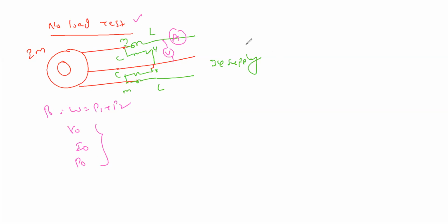What is its equivalent circuit? For a transformer under no load, we keep only the shunt elements and neglect the series elements. But here what will happen, we can't neglect the series elements here, because 30% 40% current is going in no load, so there will be a drop. Therefore, what is the equivalent circuit here now?